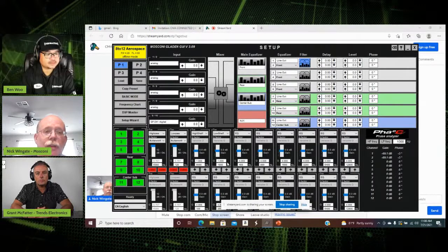A lot of vehicles do, and what's going on is either the off axis response of the speaker is not very good above a certain frequency, or it could be a simple fact that there's some surfaces in the car that are absorbing frequencies. It happens. So instead of going into the EQ section and boosting everything in the EQ, which you really don't want to do because that causes phase shifts to take place, you can use what is known as a high shelf.